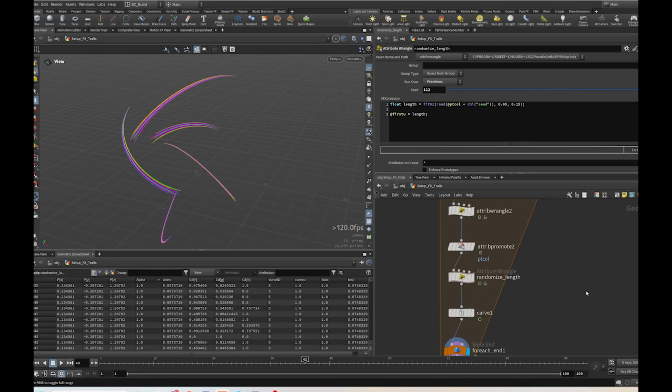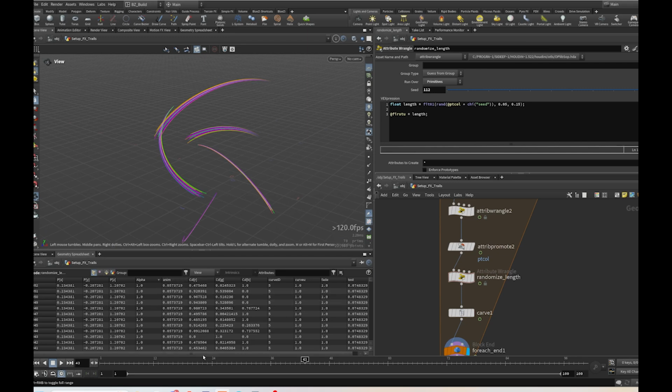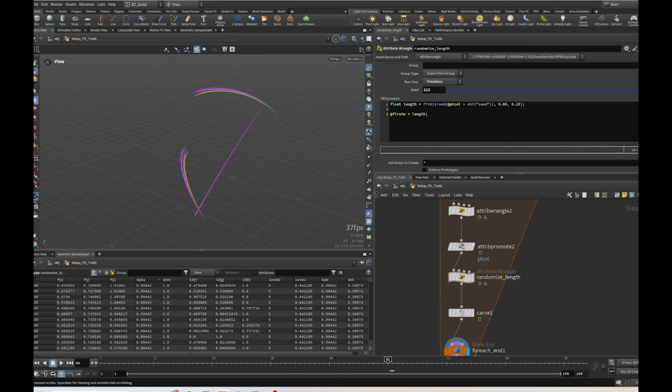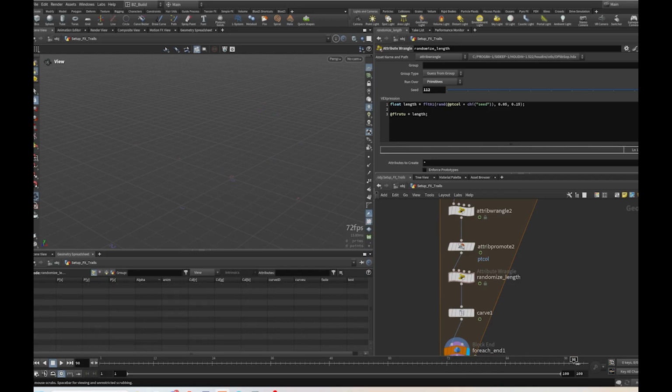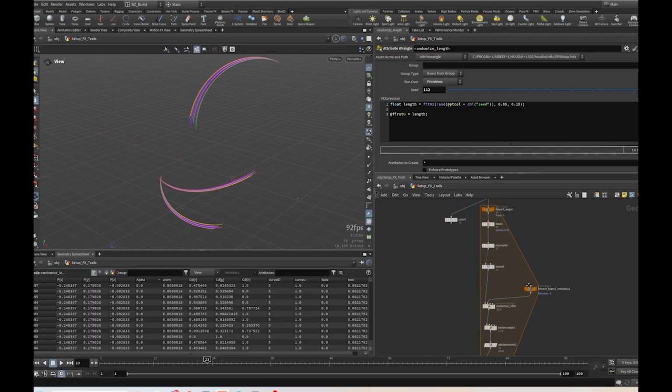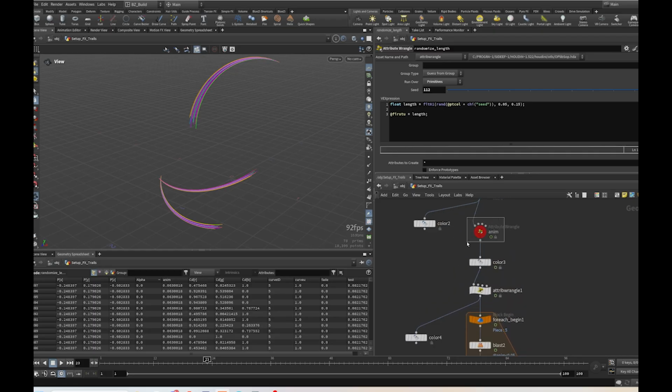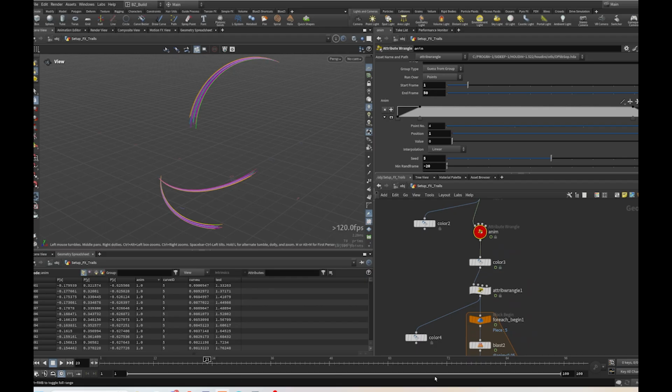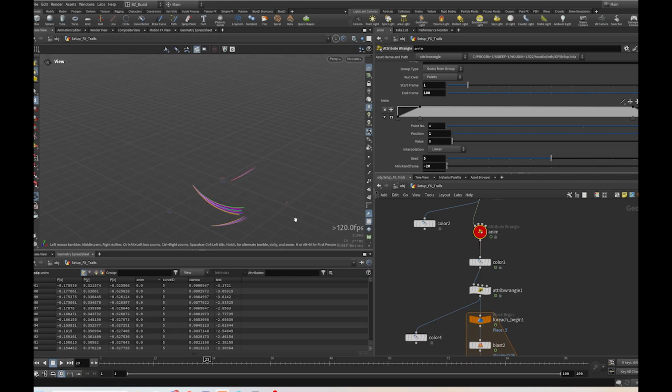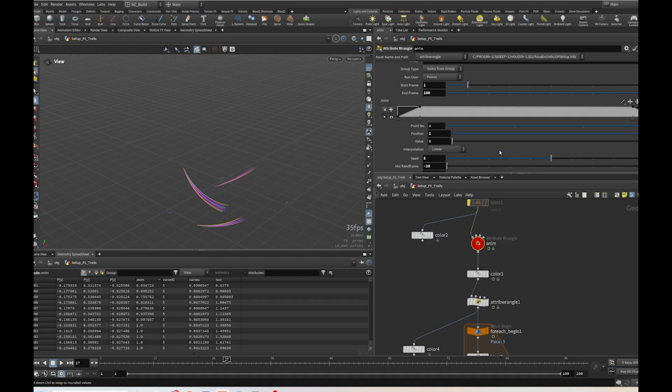And then one thing you can notice about this effect is that the trail ends kind of quickly. It will end around frame 60 to 70, but we want the trail to happen for the whole frame range. So we need to extend that. So if we click on this ending range here, and we have from frame 1 to frame 100, so let's type 100 here, and you can immediately see that the length of the trail will be shorter, and also the speed will be slower. And I think it's probably one of the drawbacks of this triangle here is that you cannot control the speed and the length of the trail separately.